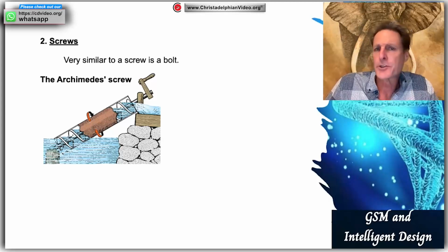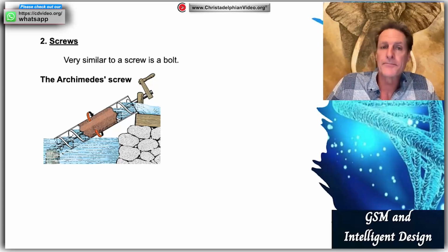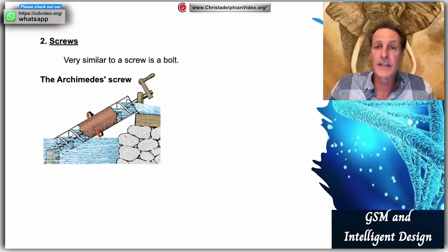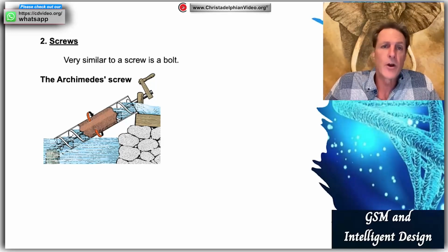And as we said, a screw or bolt is a type of fastener, typically made of metal and characterized by a helical ridge known as a male thread, external thread, or just thread, wrapped around a cylinder. Some screw threads are designed to mate with a complementary thread known as a female thread or internal thread, often in the form of a nut or an object that has the internal thread formed into it. And again, much like in our case of gears, screws, nuts, and bolts are used extensively in our man-made world.